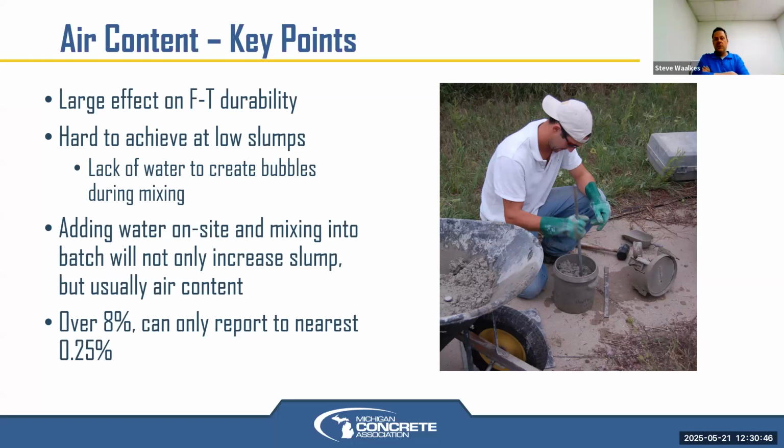if the driver or a QC person has the same air entraining admixture that was used and knows how much to add based on consultation with the right people who are knowledgeable in those things. That can be mixed in. Same thing: water and admixtures can be adjusted on site. You mix it in 30 revolutions and then do another check test. The issue with high air or high slump is that you can't take those materials back out, and most specifications do not allow adjustment.